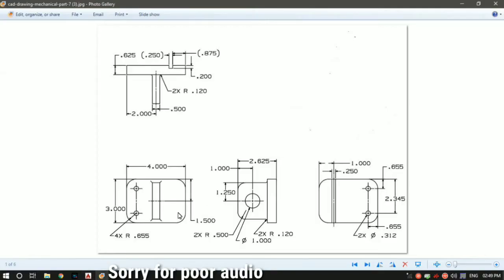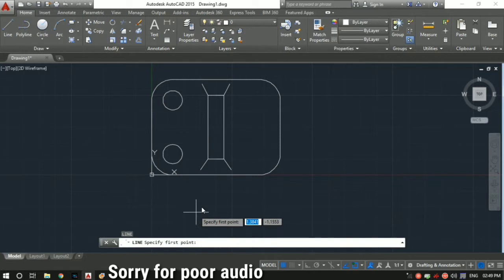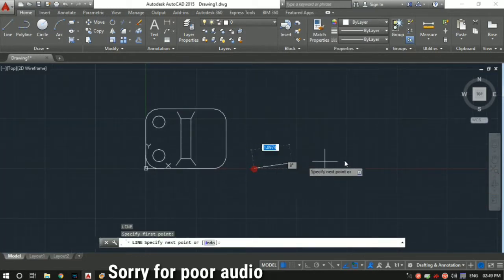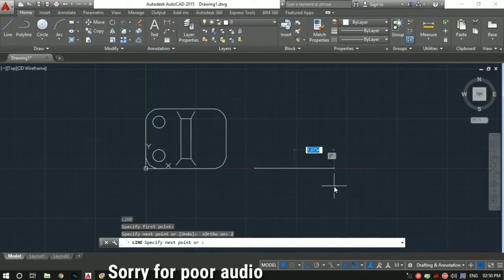So basically, so far we have made this particular drawing, and now let me make this drawing. This is basically a rectangle followed by another rectangle, and the smaller rectangle's dimension is 2.5 meters by 2 meters. So let me make a rectangle. Let me choose the line function, L followed by spacebar, then make a line of length 2 meters, which is parallel to this red axis, so that is the x-axis. So turn on the ortho mode too, then make a vertical line of 2.5.